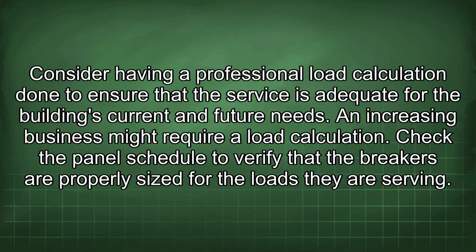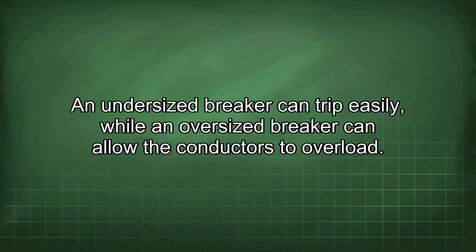Consider having a professional load calculation done to ensure that the service is adequate for the building's current and future needs. An increasing business might require a load calculation. Check the panel schedule to verify that the breakers are properly sized for the loads they are serving. An undersized breaker can trip easily, while an oversized breaker can allow the conductors to overload.